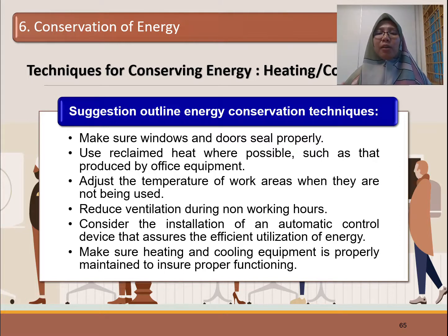So this will affect your conservation of what we call energy. Okay. Number 2, use reclaim heat where possible, such as produced by office equipment. So this is more for overseas because they have the winter weather compared to us in Malaysia. So we do not have this kind of heating system. Okay. And then adjust the temperature of work areas when they are not being used. Whether you switch off or you reduce the temperature where the people do not use that area. Okay. And then reduce ventilation during non-working hours.